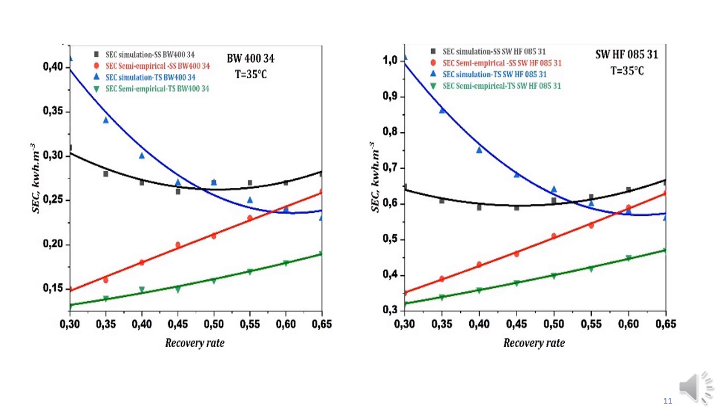The inclusion of an energy recovery device system has an impact on the semi-empirical model and its evaluation within both single-stage and two-stage reverse osmosis units. In this instance, from the figure, the simulation model surpassed the semi-empirical model across both membrane types and in both stages. Additionally, an observation is that with increasing temperature, the disparity between the semi-empirical model and the simulated model becomes more pronounced, particularly at recovery rate equal to 13%.